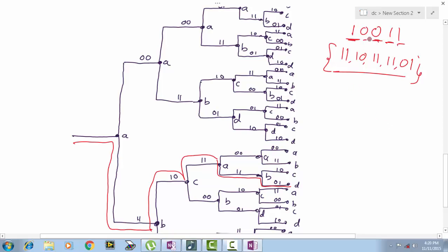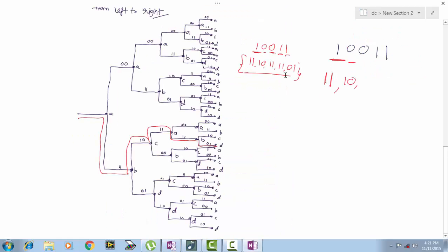But remember that the message sequence length is 5. That is the reason why I have drawn 5 branches of the code tree. If the message sequence is longer than 5, you need not draw the rest of the branches, because if you look at the figure carefully, after 3 branches the structure repeats.